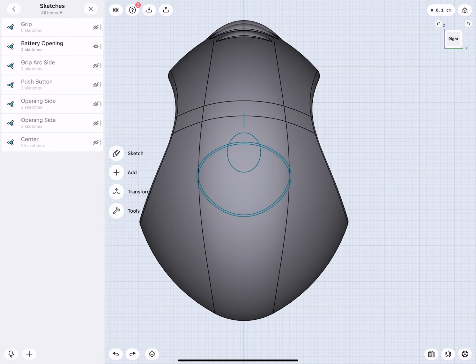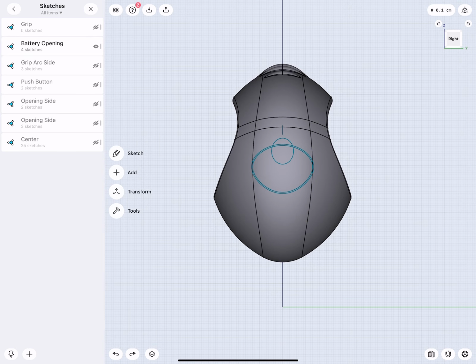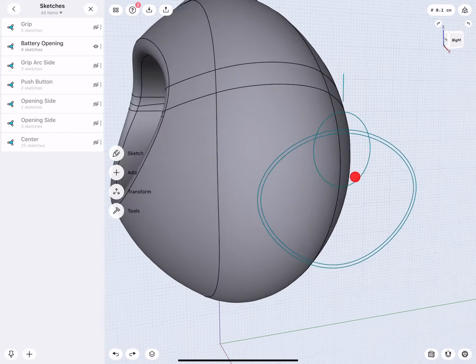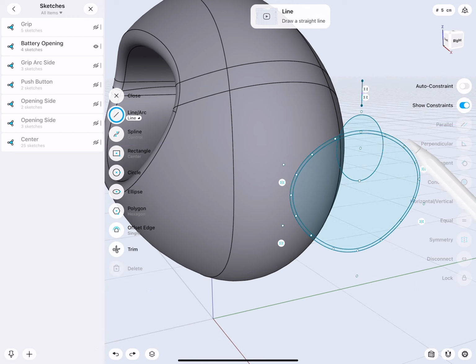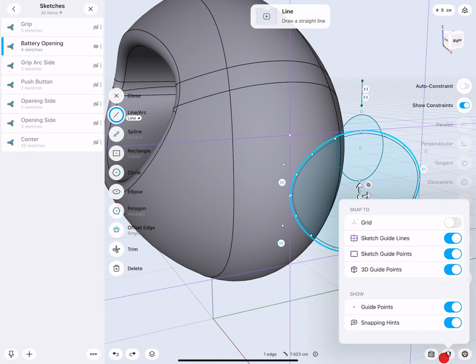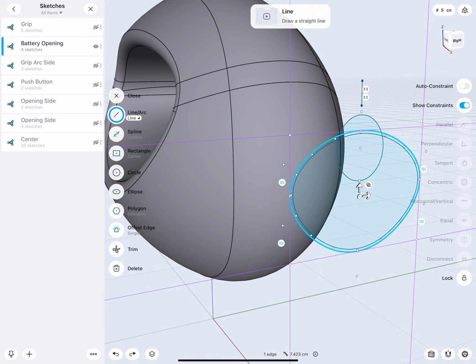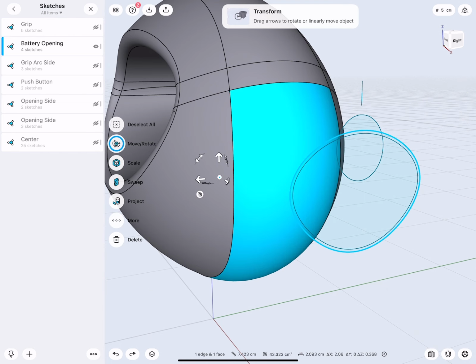Here, in this case now, all I actually want to do is build something right into the surface. So it's not meant as a prototype in terms of having a piece I could remove, but have a structure on the surface I could at least touch or feel. And I have an outer profile and the offset inside, and here another shape. So I will select the outer one, then select the face and do project.